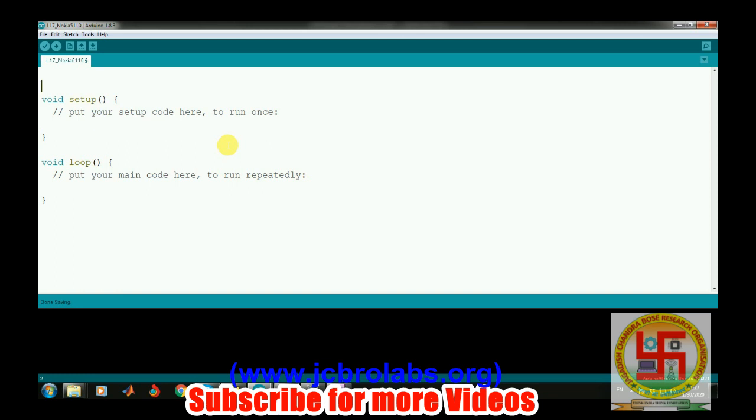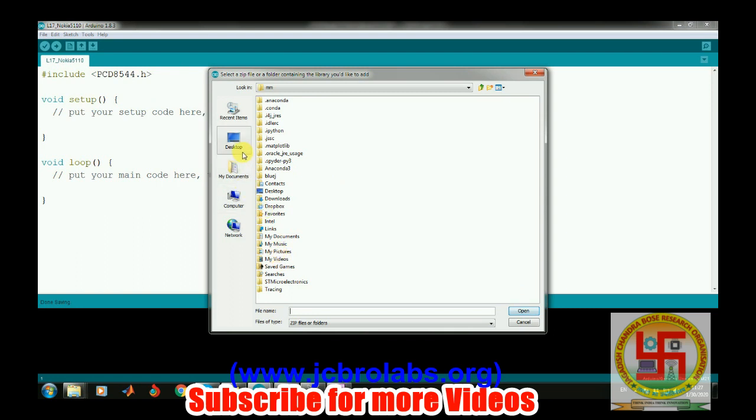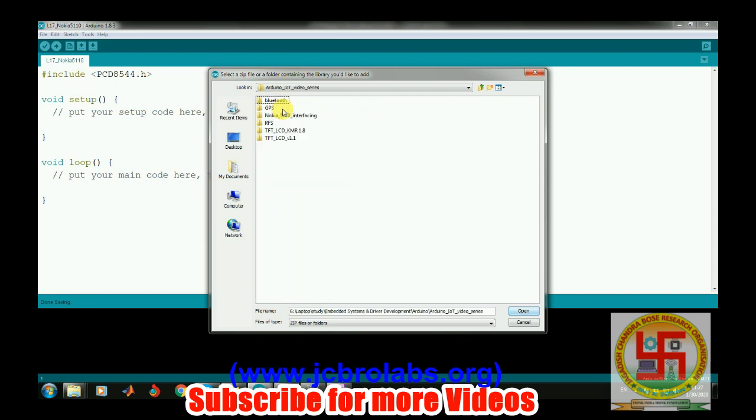So let's add the header file: hash include pcd8544.h. One more thing, you have to download this header file prior to installing it, and it is easily available on the internet. This is an Adafruit header file. You can then add it to the library from include library, add zip library, and just give the path where this header file is stored. In our system, it is stored here, pcd8544_master. We will also add this header file to our website, so if you wish to download it, you can download it from there as well.